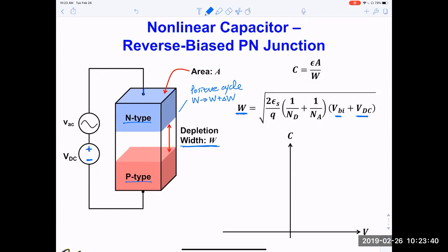When the reverse bias more, okay, you exposed additional layer, you pull the electron back. So what you are left here is a positive charge, okay? This positive charge, even though it comes from donors, these are ions, it's not mobile itself. The electron is mobile. So the electron is responding to your small signals. When in the negative cycle, it will come back and neutralize this donor ion. So it behaves exactly like a parallel capacitor, okay? And you know, first time you may want to think about in detail how electron actually cover these ions, but it behaves exactly like a parallel plate capacitor.